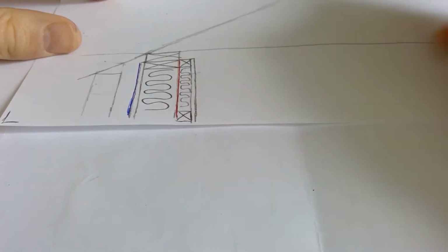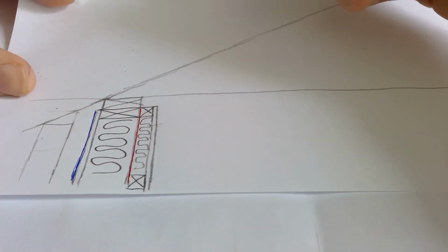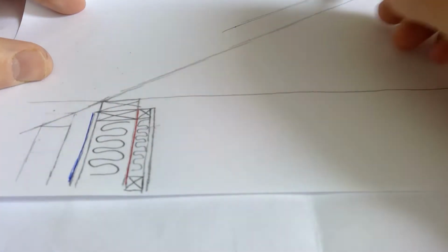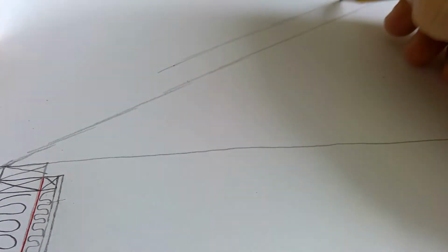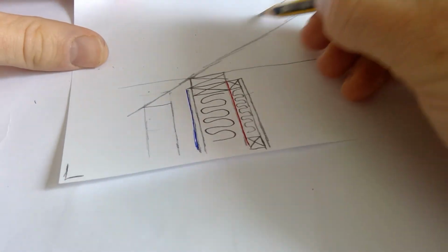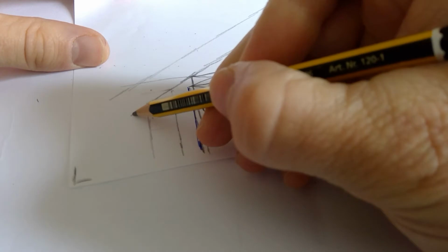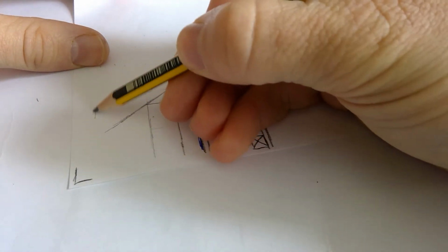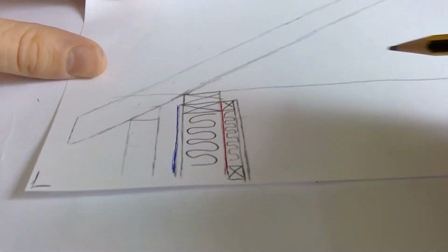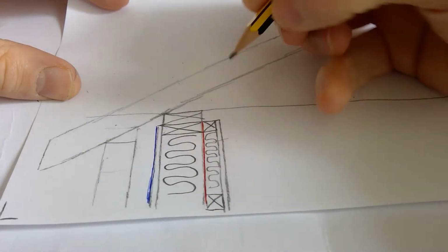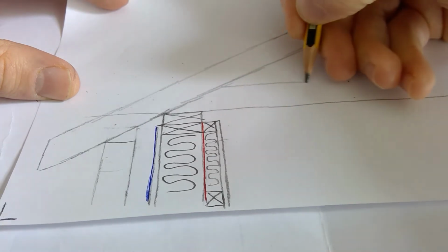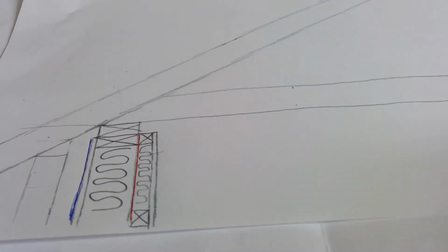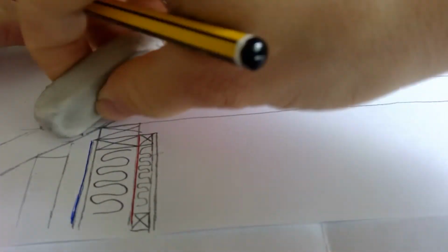Okay, so we have the position of that now. Those trusses and rafters are always 150, so we'll go out our 150 here. Extend that on. Up there. Bring it back down here. How far down here you can decide yourself. Somewhere enough so you can fit a fascia and a soffit and a gutter in. And we have 150 millimeters here, so run that across like that. Alright, now you can rub out a few of these bits.